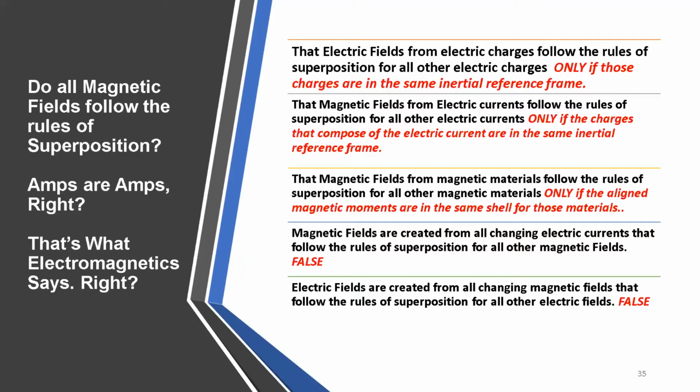We tested a number of different materials, not just these. These are some examples. So if the charge moves differently in these two materials, the magnetic field that each one of these two materials must be seeing from the other one must be different. And it's different because the drift velocities in these materials are different. They're radically different, especially for CVD graphene, which is flowing current at 10,000 meters per second, and copper is doing 10 millimeters per second. So the two magnetic fields from these two ribbons are definitely much different.